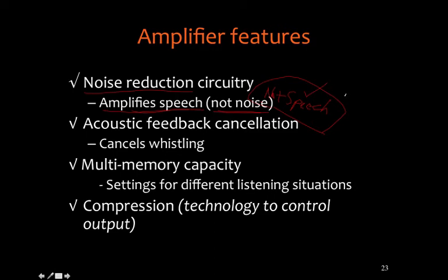So if the energy is mathematically predictable and stable and known, we can eliminate non-speech types of noises, like engines. This is a primary focus of air-to-ground communication, and other kinds of military applications, like from tank to tank or from command to tank. Again, you can tell that the sound quality is a little bit different, but it's mostly intelligible. But this is a critical problem when the background noise is itself speech.